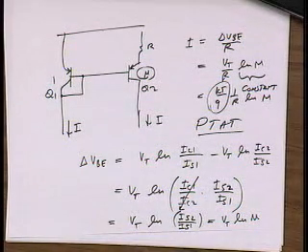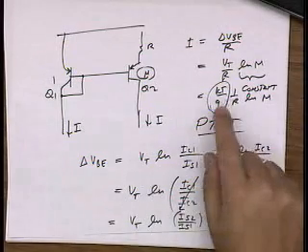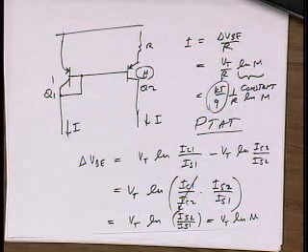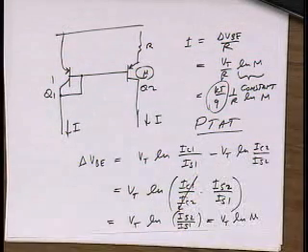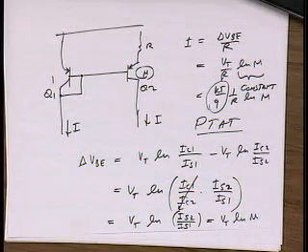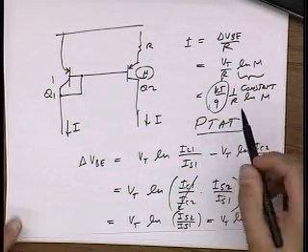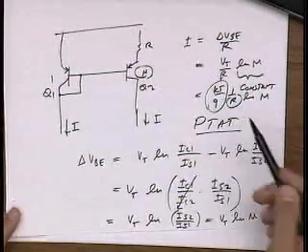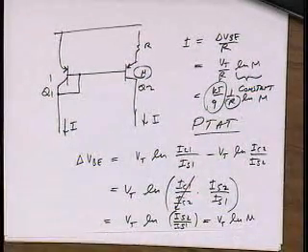But for another, maybe we have something else which is inversely proportional to temperature, or roughly so. And so we can use the temperature coefficient of this current mirror to cancel out the temperature coefficient of something else. For instance, if we were so lucky that R were proportional to temperature in this equation, right, then we would have something that would be temperature independent.